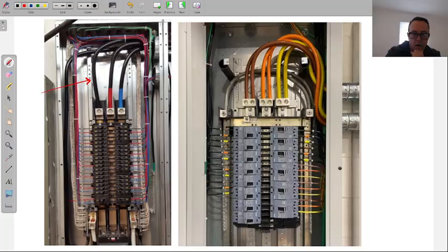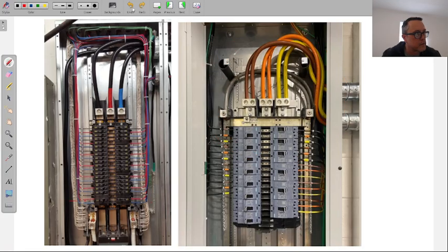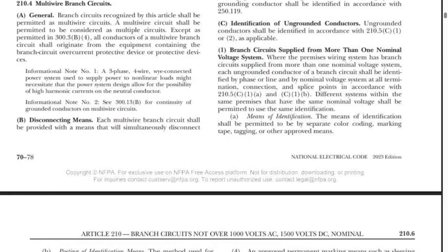But you'll notice these large conductors coming in on that one, they're using phase tape to identify. Now, it is very expensive to buy an entire large conductor, 250 kcmil, 4/0, these big numbers, as one color. So a lot of times the customers will opt for solid black all the way through with an identifying phase tape, which is what's being pointed out here. Means of identification, tape being the most common. We could tag them. I've never seen tags, other than big giant conductors might have tags. Color coding, marking, but like I said, most of the time we will use tape.